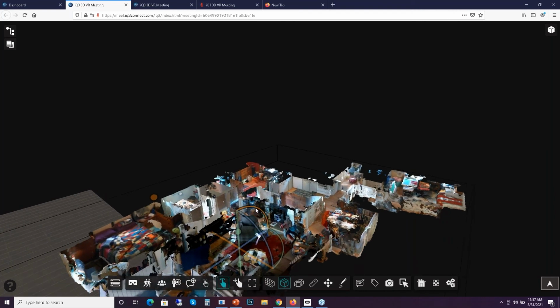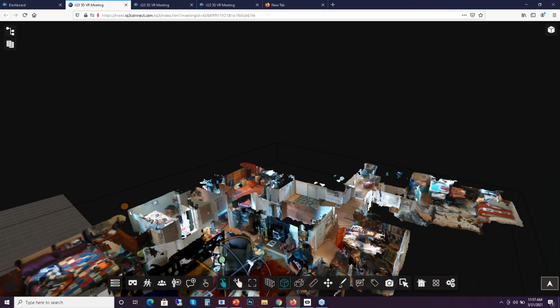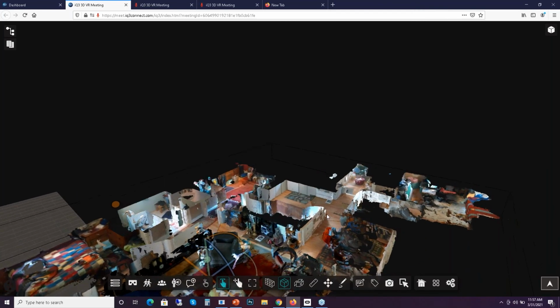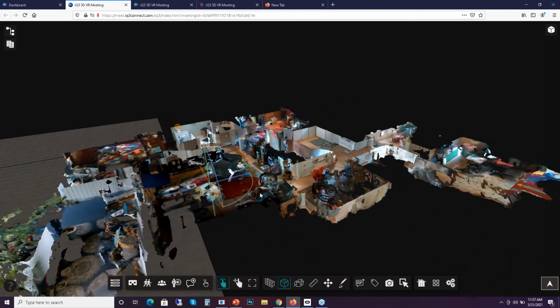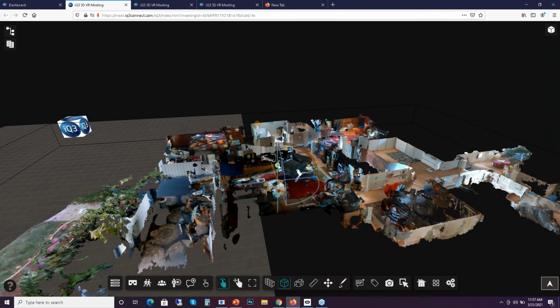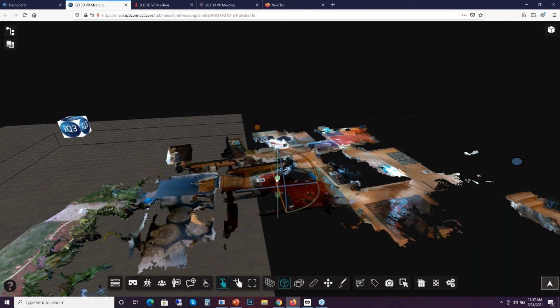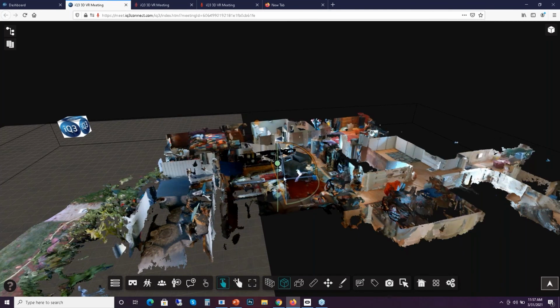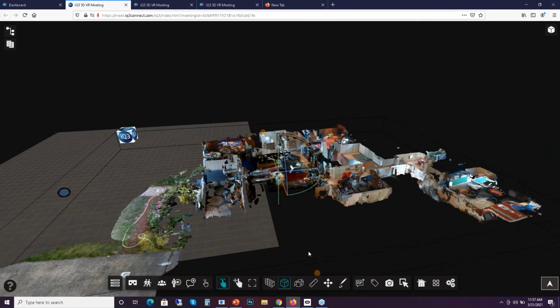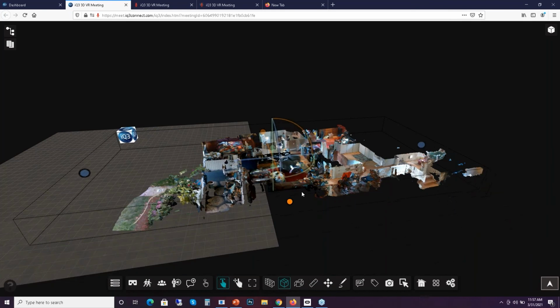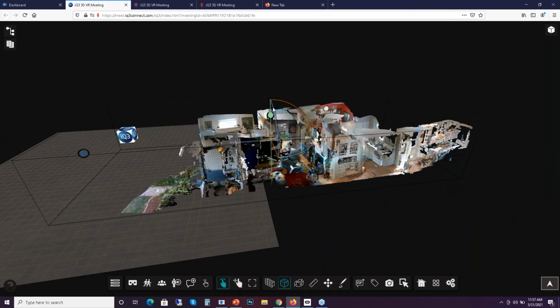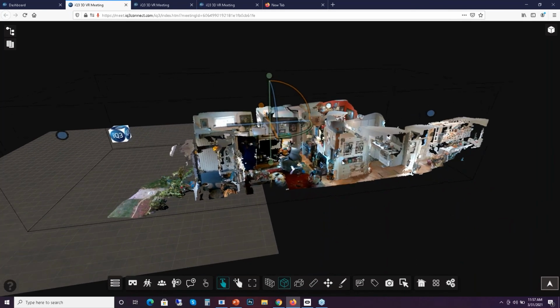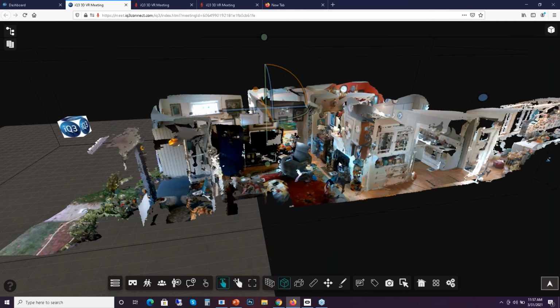Also, as you had highlighted, the April tags on the exterior prior to moving inside, the auto registration, and capturing those April tags with a GNSS rover allowed me to take the data set and move it into a real world system where it can be integrated with other data, such as data captured with a UAS or terrestrial scanning device, to supplement or complement each individual set's values.